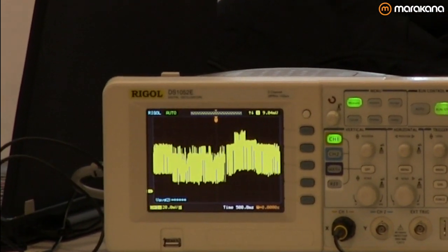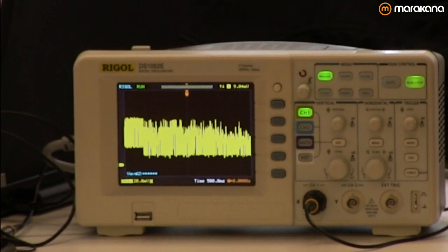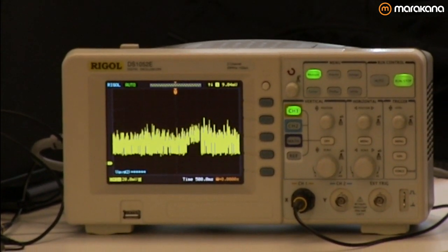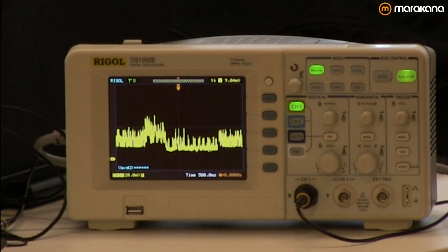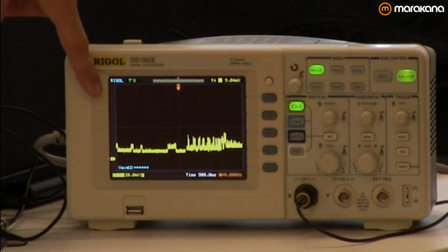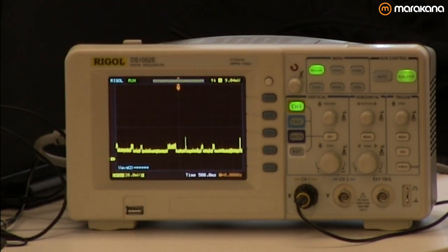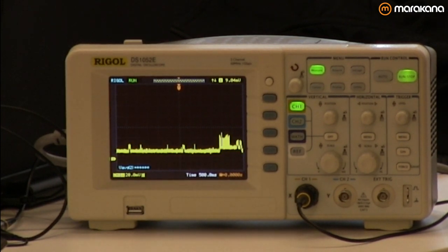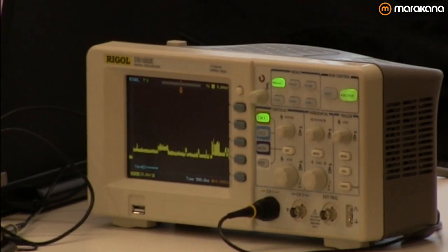Cellular has a lot of funkiness with the power. That's why I decided to run that benchmark. But you could run something like a CPU test, where you just run some software at 100% of the CPU, and that test will just look like a straight line. You probably can't see this, but basically the power jumps up and then it stays at a constant power rate. So that's how you do that. You guys can come take a closer look after the talk. It's probably hard to see, especially if you're over there. But that's my setup for the current measurement.